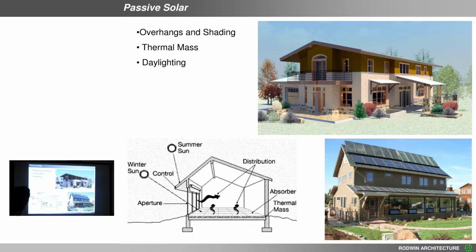This is a diagram of a similar kind of house where we're looking at the sun coming through. This is the overhang that's protecting it. We then capture the heat. The more massive a material you use inside the house, whether it's walls or floor or big planters or rain barrels, whatever it is, if you can have a massive material that can capture the solar radiation directly, you're able to store the heat inside the house. So both of these are examples of good passive solar designs, as long as that's the south side and that's the south side. And you can see how the winter sun comes all the way deep into the house and warms up the house, but the summer sun is blocked.